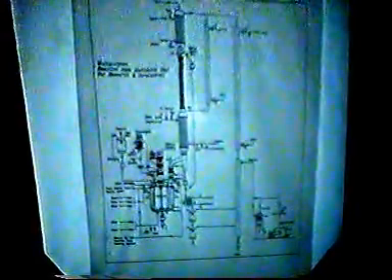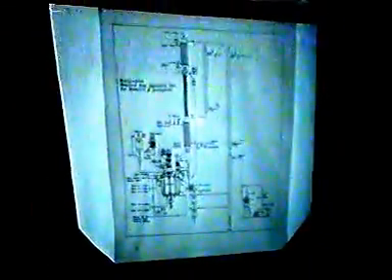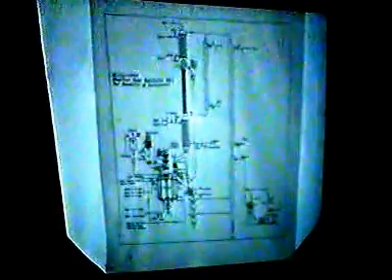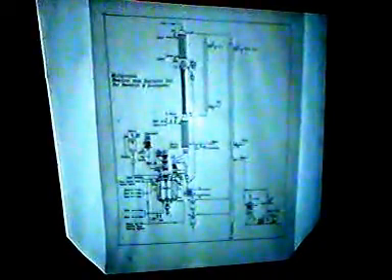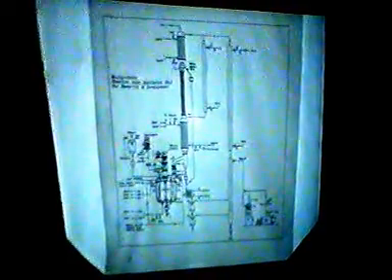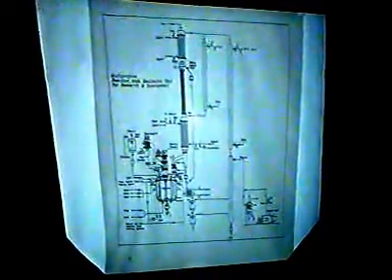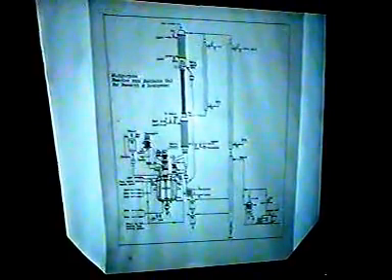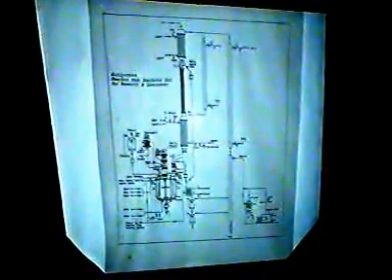The vessel has an adjustable variable speed stirring system having a turbine or anchor driven by a 3-phase flame-proof motor attached to a gearbox. This is the stirring system which you can see with the belt and pulley drive, wherein we can change the revolutions per minute of the stirrer by selecting the proper ratio. The drive provided is a belt and pulley type.